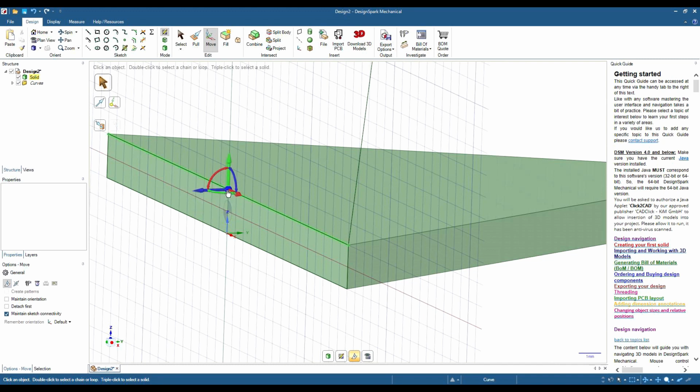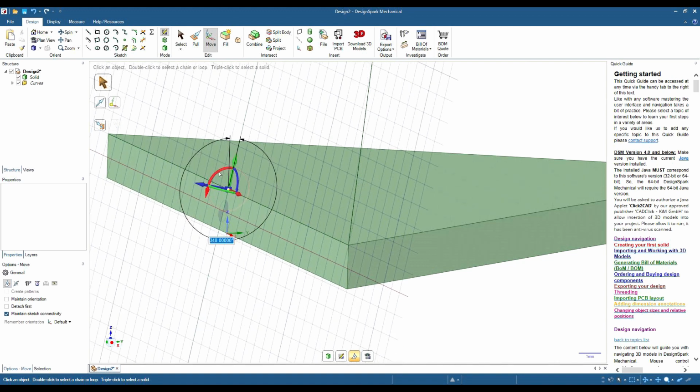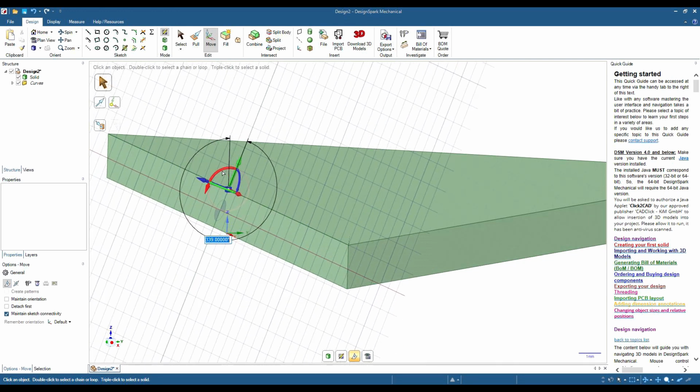Our pivot point needs to be on the top line. Rotate our grid in again, spacebar, minus 19.4722 degrees.